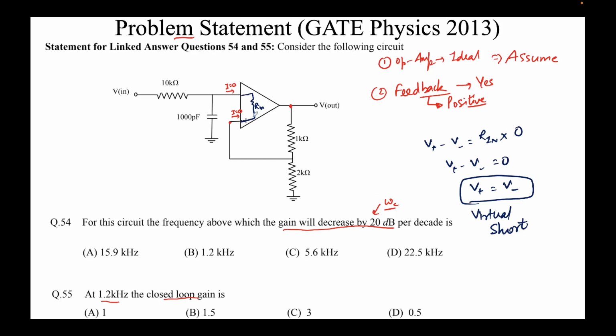It's just the peculiarity of the op-amp that it appears as if the inverting and non-inverting terminals are at the same potential, and we denote this effect by using a dashed line between these two points. So this denotes that these two points are at the same potential, not joined by a wire. Now, let's go ahead using this information.